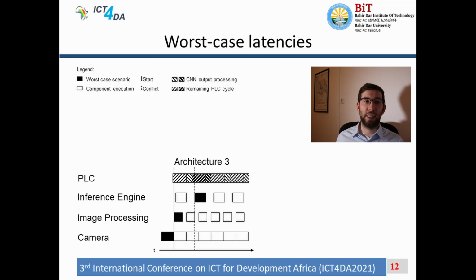Last but not least, there's a third architecture, which is a little bit more complex. Since our PLC shares the same memory with our convolutional neural network, it is possible to exchange data even during the PLC cycle. Thus, it is possible to pre-calculate when the inference engine should finish its job, to pass the extracted data up to the PLC.